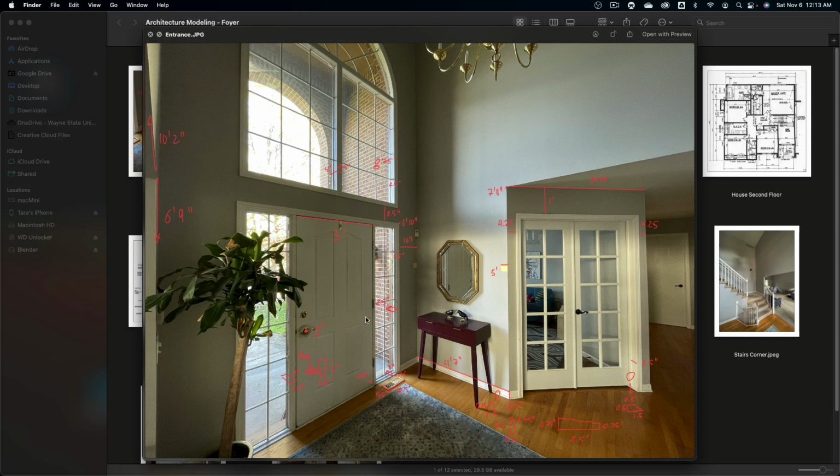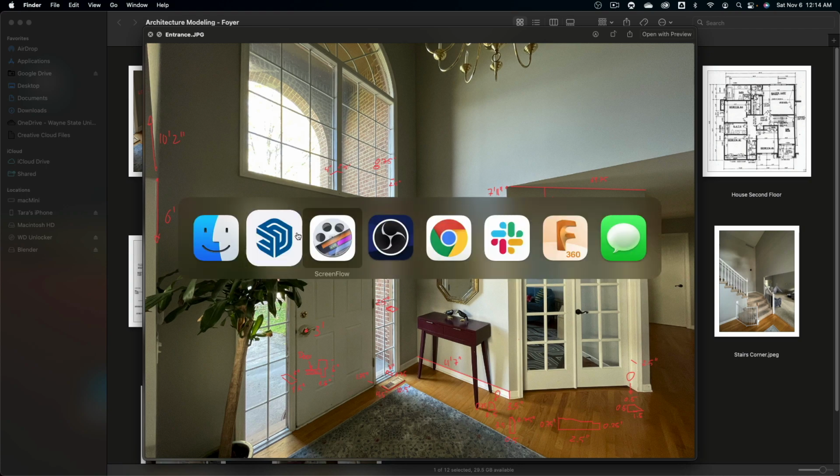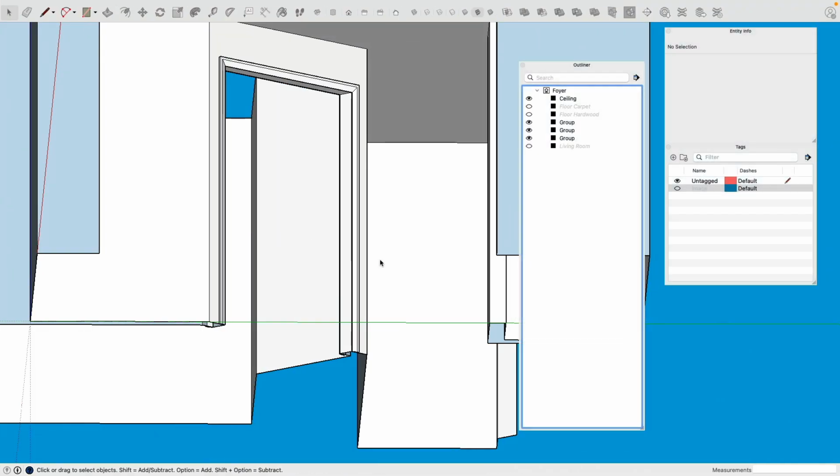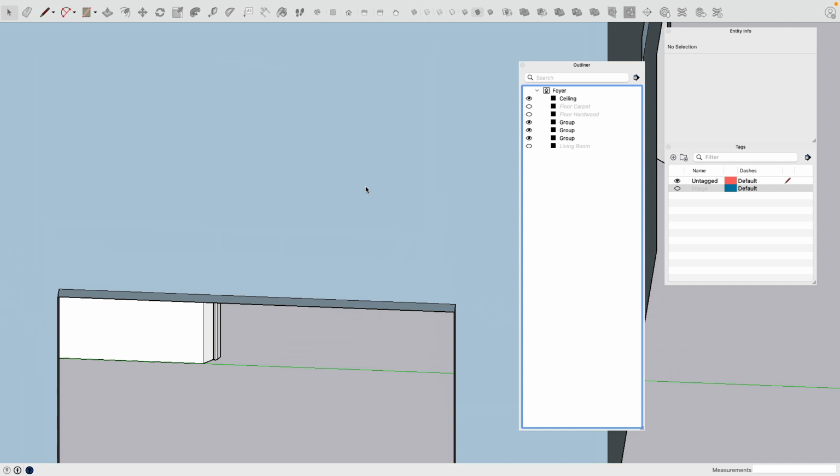Then, since we're working on that door, we can continue working on that door. Down here is another small detail. So the doors open to the inside of the room. So that means that there will be a little bit of a gap or a distance, 2.5 inches, and then there is a stopper. The stopper is kind of like 1.5 inch and half an inch. And then this is 2.5 inches to the inside. Cool. Let's do that. 1.5 and half an inch might be possible to memorize.